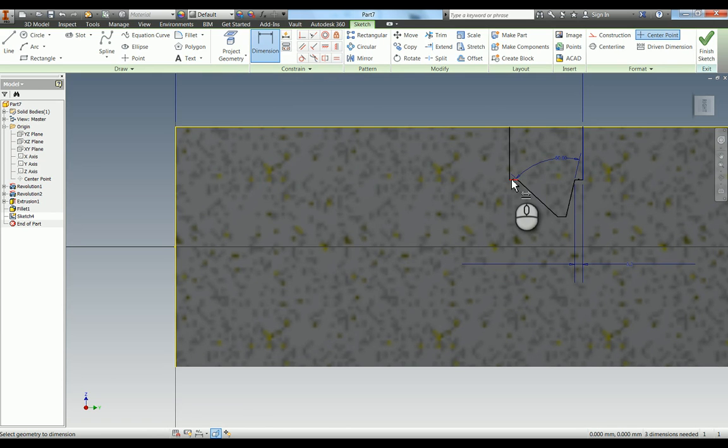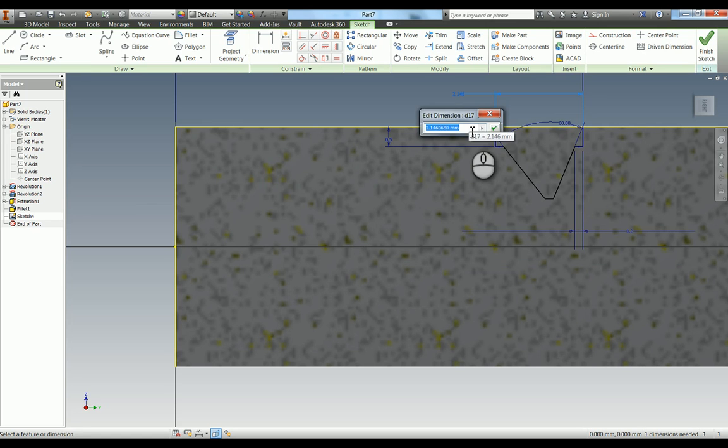So we know it's 5mm, and this outer one here is 6mm, so that'll be 0.5. We're going to put this dimension in here, which is 1.4. And you can see this here, so I'm going to add equals to these two lines. And now you can see we're fully constrained just down here.